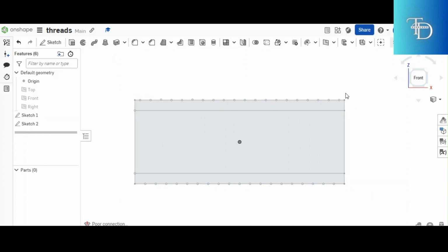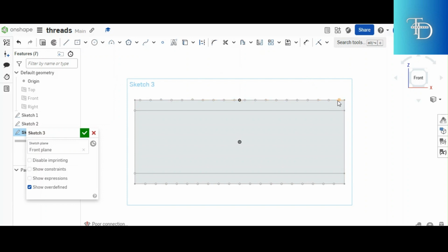What you do now is you join your half pitch with the opposite corner. That is the next thing that you are supposed to do. You join your half pitch with the opposite corner right there, like that. And then the next thing, that pitch line right there, you're gonna use it as a reference to create what? To create the thread's edges. Now that's the point where you start creating your what? Your V's. Hence this thing is called a V thread. This is what you do.